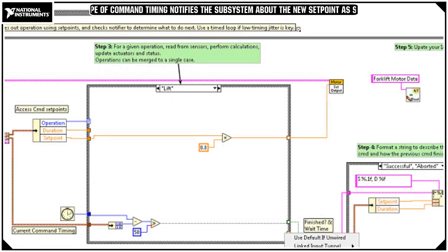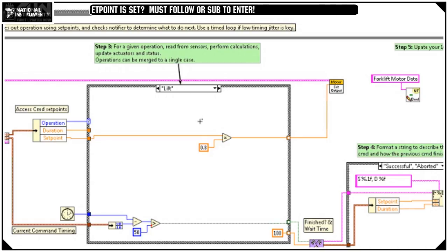And then drag that across. I can just drop a 100 here. This is the default wait time, and since our motor timeout is 100, we wanted to move on at least at that point. So we did that, great. That's all we need to do for our lifting mechanism, right? We just want it to take the joystick input and lift at 0.8 rate of the motors.